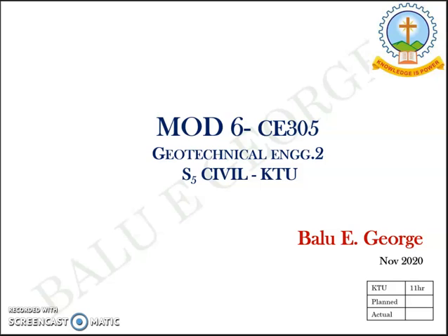And in the second module, we discussed lateral earth pressure at rest, active and passive cases. We briefly discussed what Rankine's and Coulomb's earth pressure theories are, and we discussed the geotechnical design of a retaining wall under different conditions of surcharge, incline, backfill, water table fluctuations, etc.